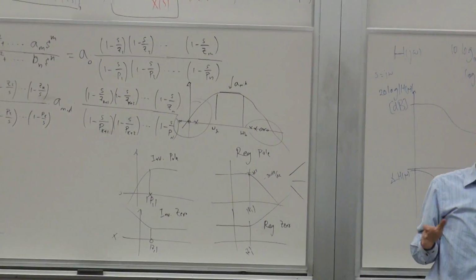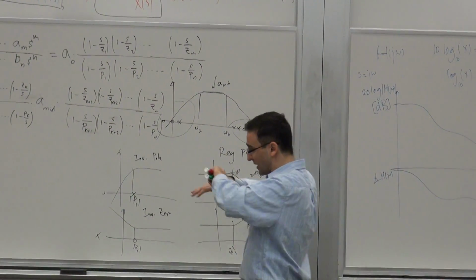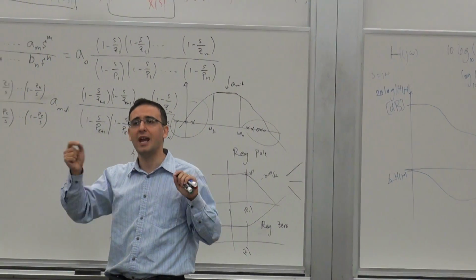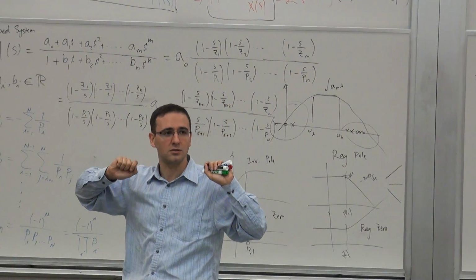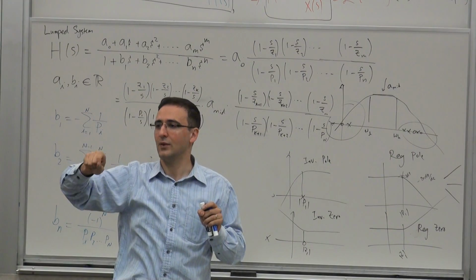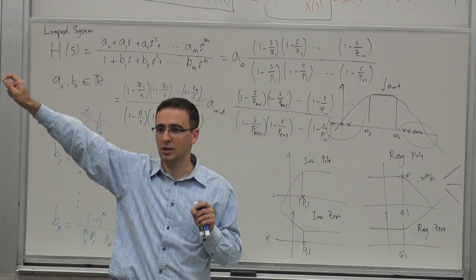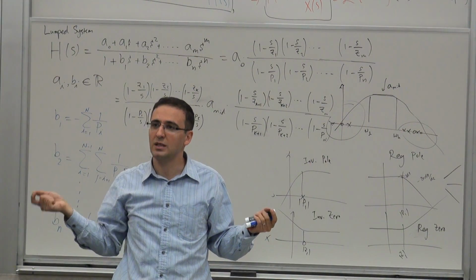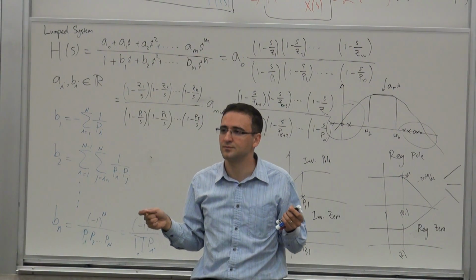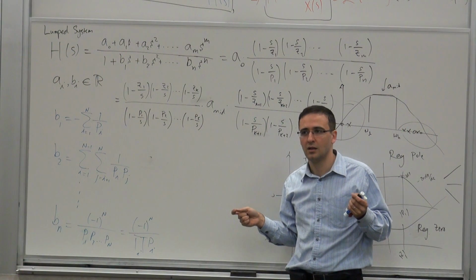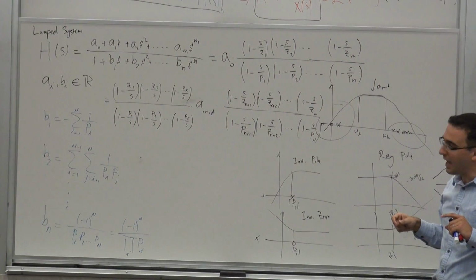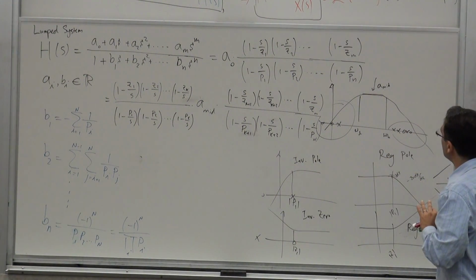So the poles only depend on the general properties of the network, while the zeros, on the other hand, would change depending on where you take your outputs. So for the same circuit, if I take the output from one node, I will get one set of zeros. And if I define another node as the output, I get a different set of zeros. But the poles would be exactly the same in both cases. Okay, so that's another thing. Now, this is just the background information we need.